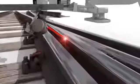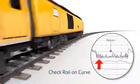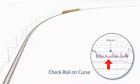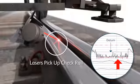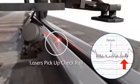Incidences of a no fault found defect need to be reported to the section manager for further investigation and recorded on the fault report. On a tight radius curve, it is likely that a check rail has been installed. If over time the low rail on the curve has head wear, the TRV can show a length of tight gauge throughout the curve. The reason for this is likely to be that the check rail is less worn than the low running rail, causing the laser to pick up the check rail rather than the running rail.